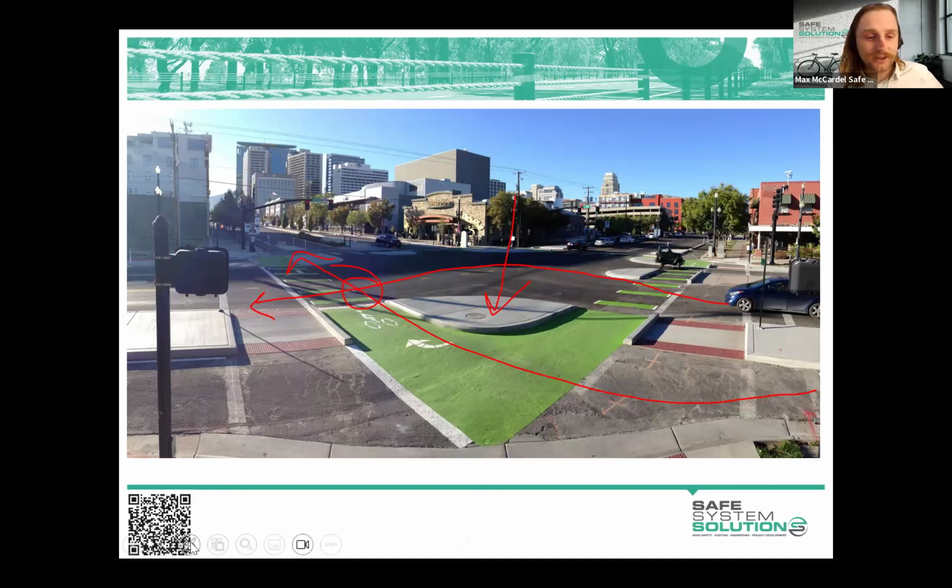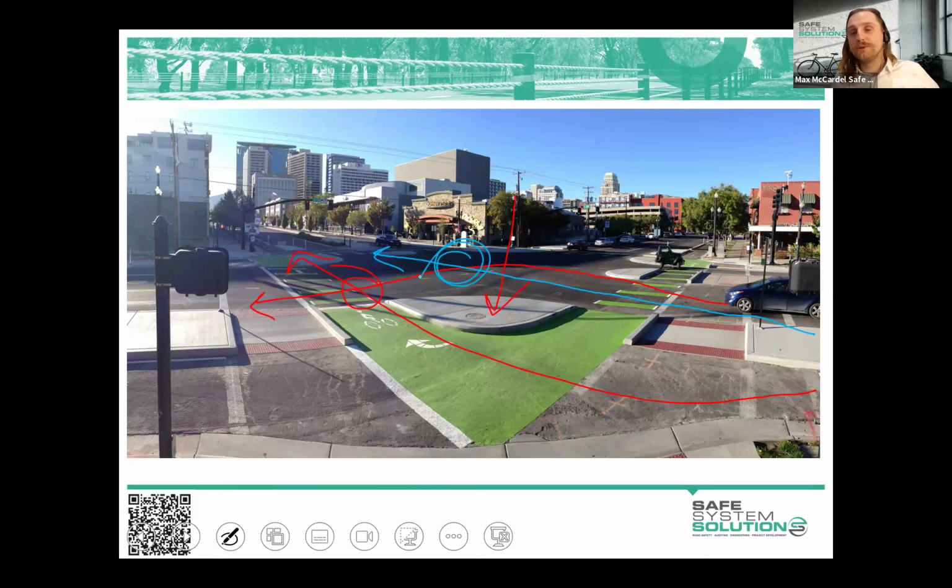I'll do a comparison. Traditionally, the way that this intersection would be set up is you'd have a bike rider on the inside lane, somewhere there. And if they wanted to go through, they're basically on the passenger side door, which is the blind spot. So left-turning vehicles and that through cyclist movement have a very acute crash angle. It's just not conducive to good sight lines. So we use protected intersections to improve those sight lines, where we do have cycling corridors.